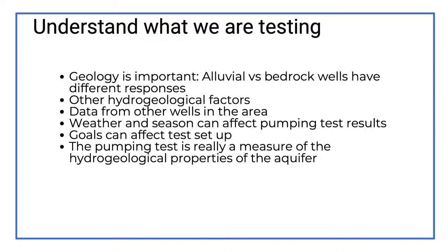It's important to understand the weather and season can affect pumping rates. You probably want to do your pumping test during the driest period of the year, so that's going to be your worst conditions, so that you can really measure the capacity of the well under the most stress, and you know you're going to be safe under pretty much all conditions then. So you want to make sure you understand what your goals are when you set up the test, and that you're really measuring the hydrogeological properties of the aquifer.